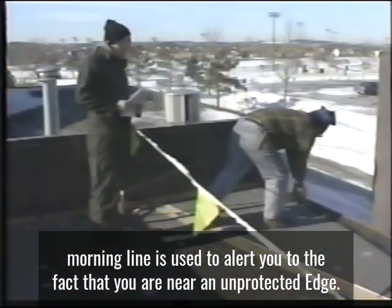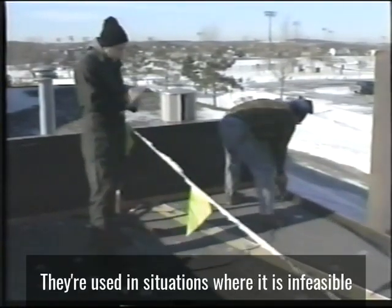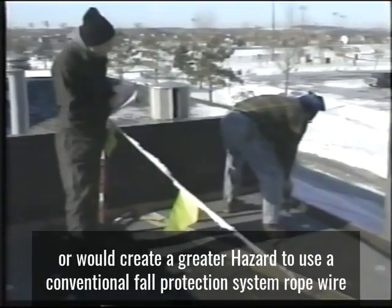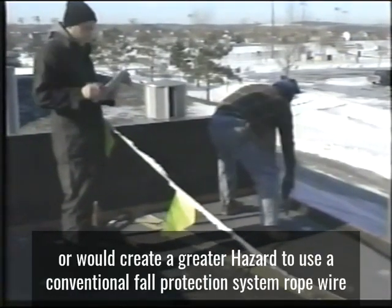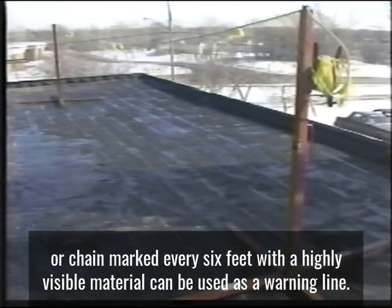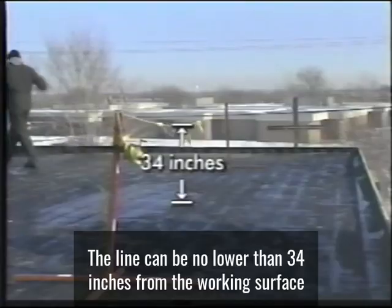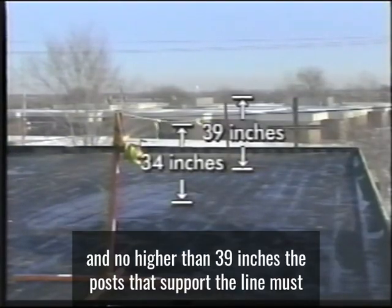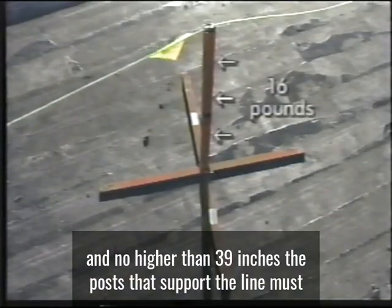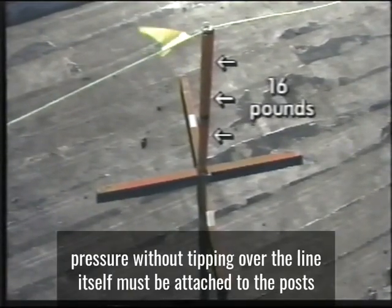A warning line is used to alert you to the fact that you're near an unprotected edge. They're used in situations where it isn't feasible or would create a greater hazard to use a conventional fall protection system. Rope, wire, or chain marked every 6 feet with a highly visible material can be used as a warning line. The line can be no lower than 34 inches from the working surface and no higher than 39 inches. The posts that support the line must be able to withstand at least 16 pounds of pressure without tipping over.